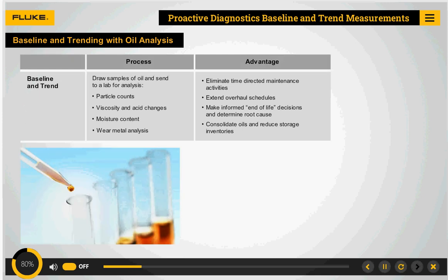Oil analysis is a quick, non-destructive way to gauge the health of an engine by looking at the contaminants suspended in the oil. When you do an oil analysis, try to draw the sample with minimal disturbance so as to eliminate any outside contamination, and use a small clean bottle that can be sent to a laboratory for analysis.